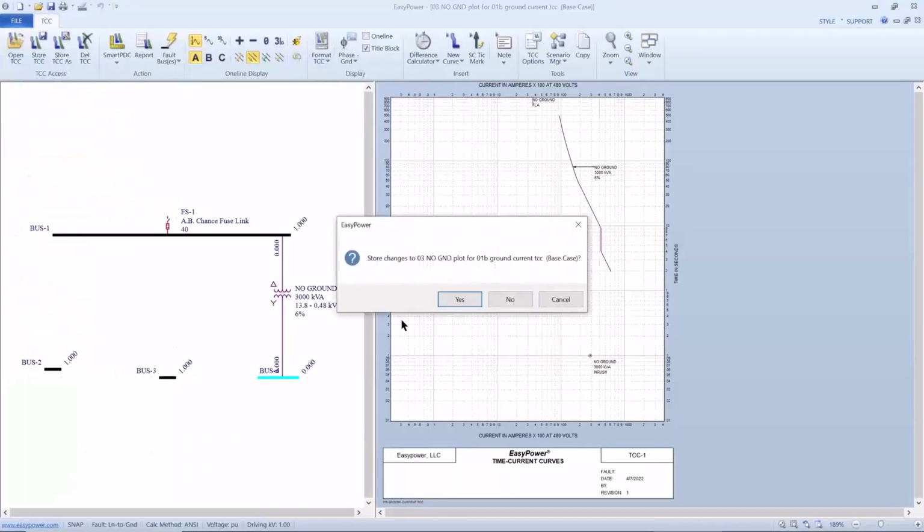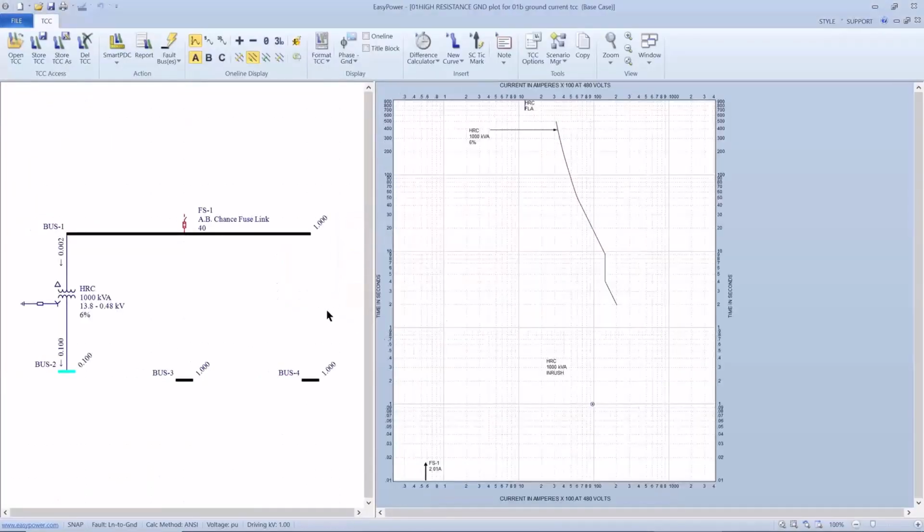So the takeaways here is if I'm focused on primary protection, I need to take into account the situation on my grounding transformer, specifically for a line to ground fault. Now for a three-phase fault, it doesn't matter because now we have full current going through the fuse, and we need to make sure we stay clear of that 100% curve.